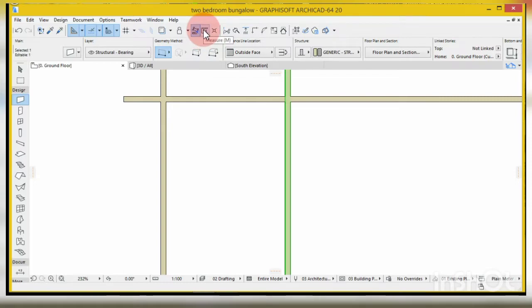You can see measure, or you just simply type M on your keyboard. So you can see I want to measure this to know what is here. You see I have 3,450. Remember my wall was 150. That means 150 plus 3,450 is 3,600. That means it's from here to here, that is 3,600. So that's not what I need.